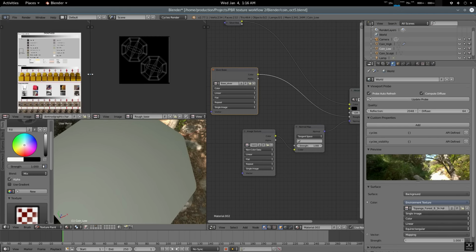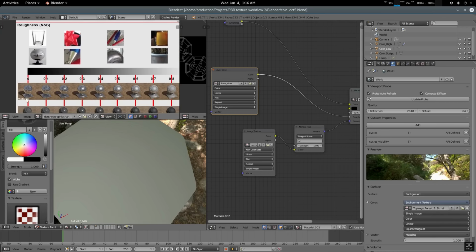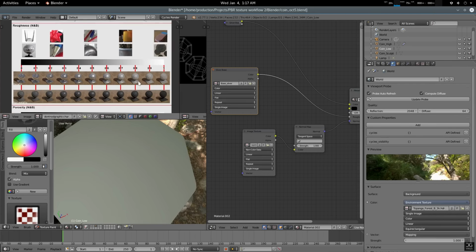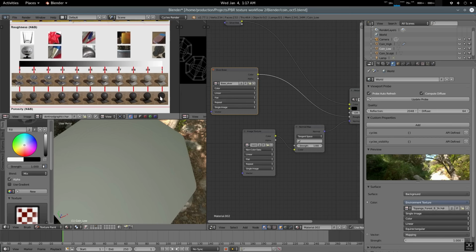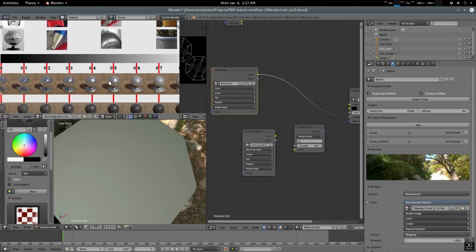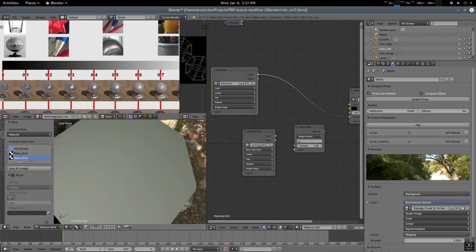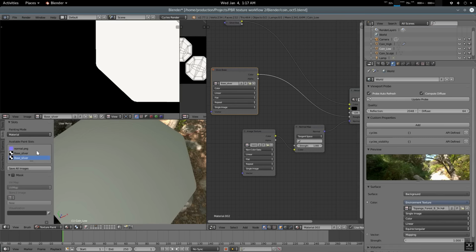So we are using a metallic shader here, so the roughness should be from the metallic values. All right, it has the non-metallic. Non-metallic is reverse, and metallic is here. So white is white. And all right, so we need something like 0.3 to 0.4 type of glossiness. I mean the roughness. So let's slot it out here. So this is our base silver.